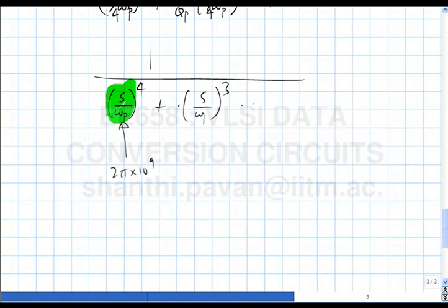Once you've finished all the calculations with 1 Hertz, it's very straightforward to scale the whole thing to any frequency you want. If you want to change everything to gigahertz, then you convert every inductor, if you got it in henries, you will get nanohenries. If you had farads, it will become nanofarads. You understand?